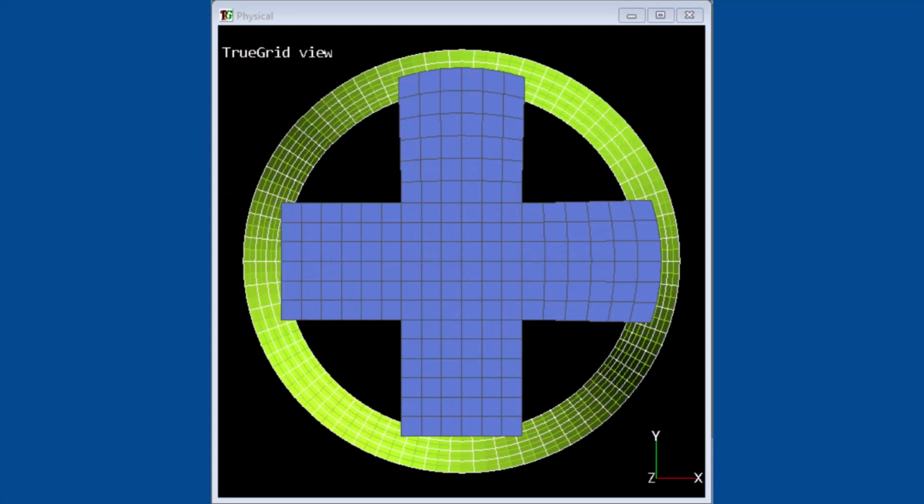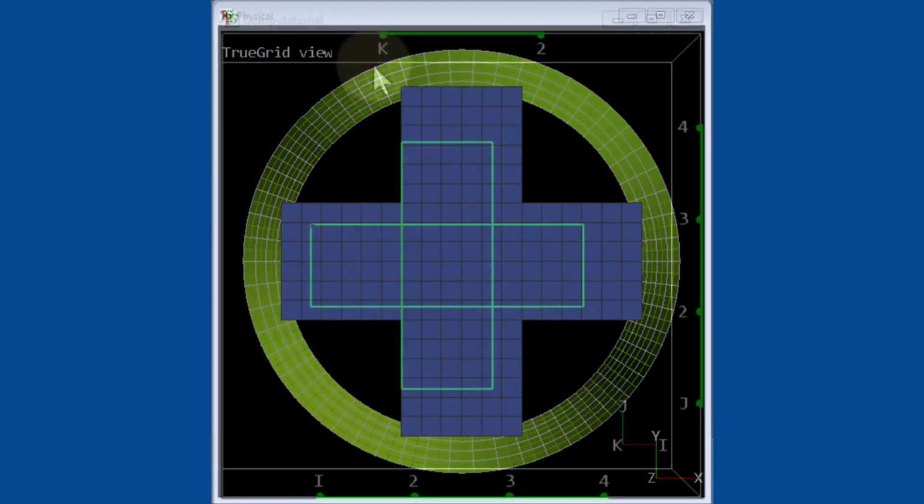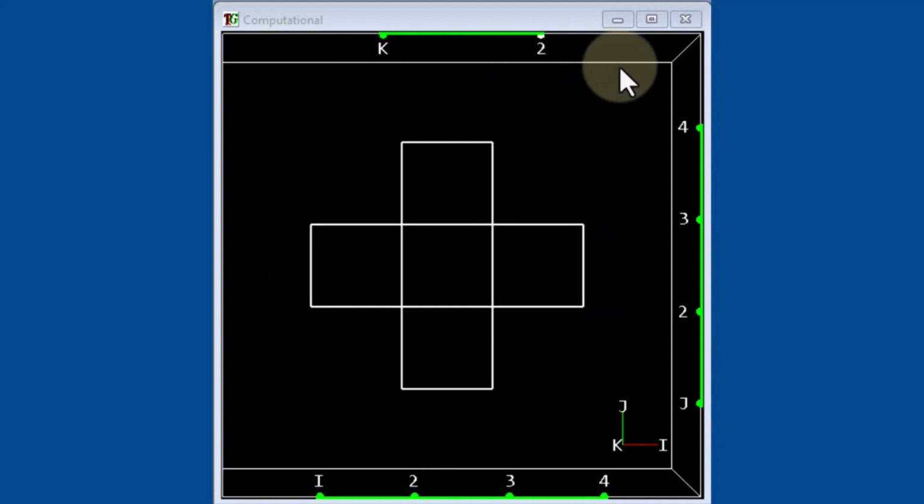Use the undo option 4 times to undo the projected faces. Notice the 3 index bars along the side of the computational window. They are made up of a combination of dots and bars. Notice that the index bars have a dot aligned for each plane of nodes and a bar representing each plane containing faces. Notice when you select a mesh component such as a node, edge, face, or block, the index bar segments turn red in correlation with the components you have selected.